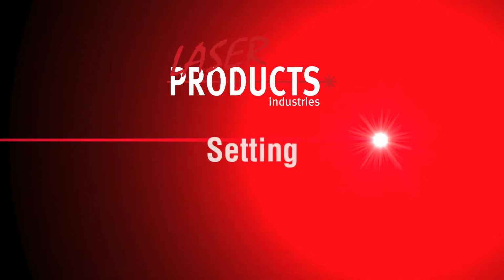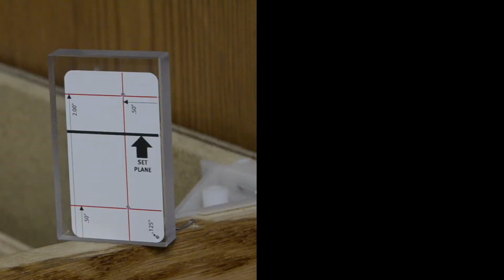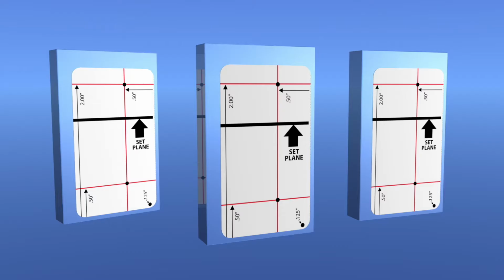In this video, we will be covering the proper way to set planes. There are two ways to set a proper plane: using the pin blocks provided for you or using a laser line generator. First, we will cover setting a plane using pin blocks. Retrieve the pin blocks that are provided for you in your case.